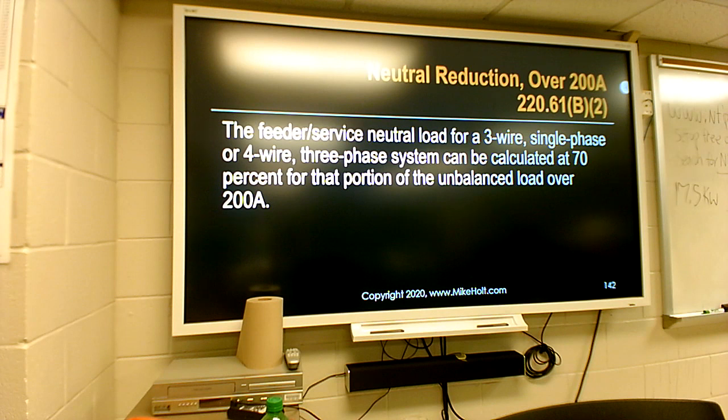The neutral, well, they're counting the neutral as part of that 4-wire on the 3-phase. They must be, because they're not calling it 5-wire. We got a plug out here on a piece of equipment with 5 wires: 3 hots, neutral and ground. They're not counting the ground.